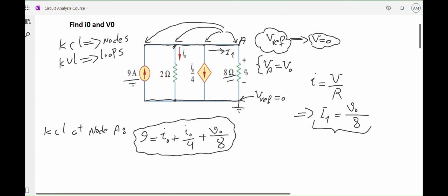And this point over here is the tail of the 2 ohm resistor. If I compare it to this point and this point, that's the head and tail of the 8 ohm resistor. Is it true that the 2 ohm resistor is in parallel with the 8 ohm resistor? Do you agree? If the heads and the tails of two resistors are connected to each other, I can say that those two resistors are in parallel.